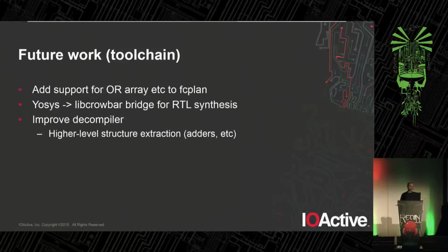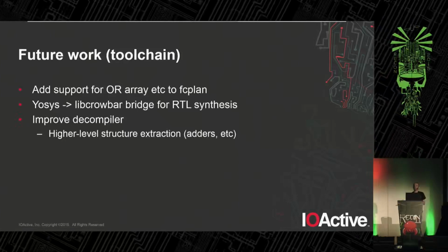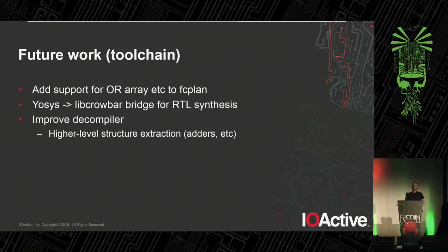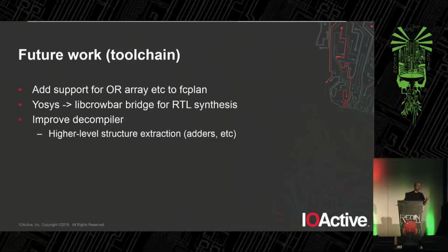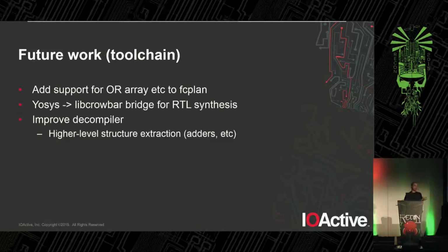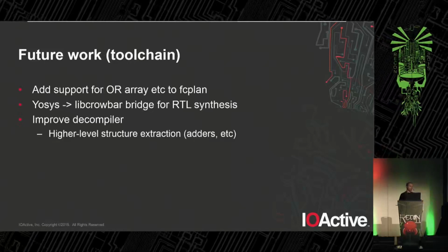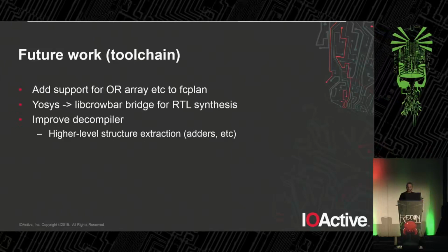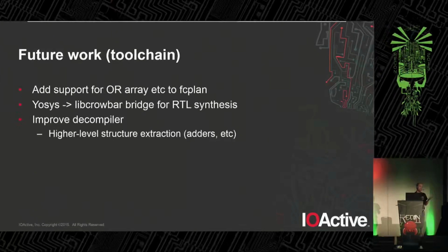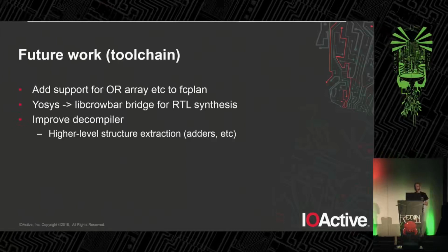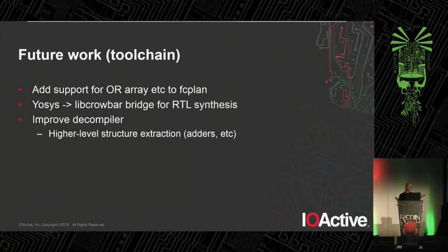on that. Figure out, okay, this combination of XOR gates and muxes looks like a 32-bit adder. This combination of stuff looks like a 10-to-1 mux. This combination of stuff looks like a Cortex M3. I would like to eventually be able to have something along the lines of FLIRT here. I do know that subgraph isomorphism is NP-complete. I don't know if I can make a randomized or approximated algorithm that's fast enough. That remains a topic for future work, but it is on the wish list, whether it is physically possible or not.